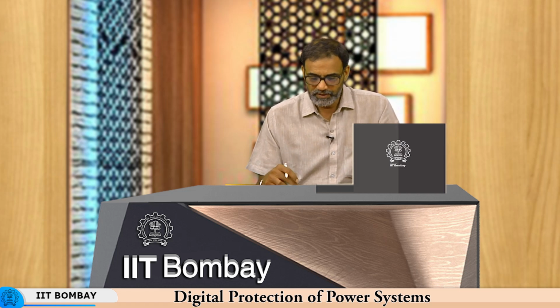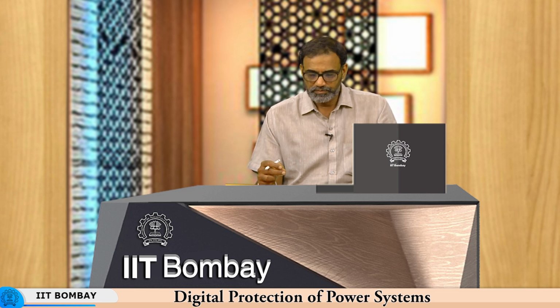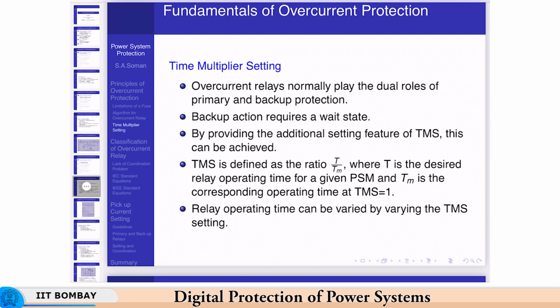Time multiplier setting is defined as the ratio T by Tm, where T is the operating time of the relay for a given PSM, and Tm is the corresponding operating time at TMS equal to 1. Okay. So, relay operating time can be varied by varying the TMS setting. Also, of course, the PSM setting. So, if you vary the TMS setting, you can shift the relay operating curve, as we will see when we look at relay coordination.